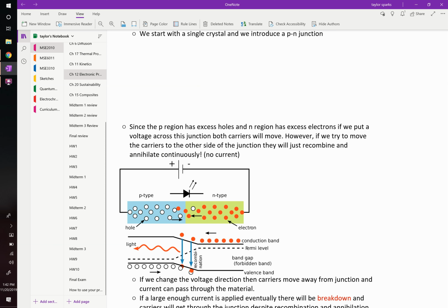It spontaneously now creates an electron-hole pair. That thing might recombine. You don't want that to happen. Instead, you want these things to drift and separate, and then you collect that current. Okay? Some do recombine, and the more efficient solar cells will prevent the recombination by making this region really small or applying a voltage to pull them away from one another. Right? But this is solar cells. Every single solar cell is just a really simple PN junction.